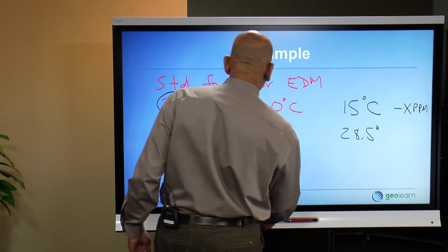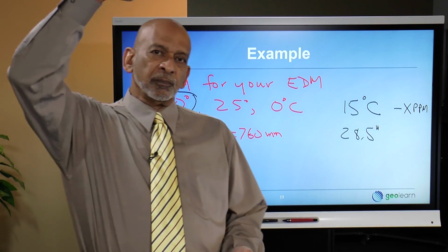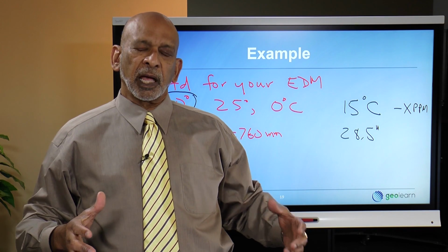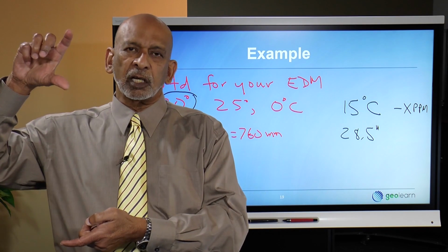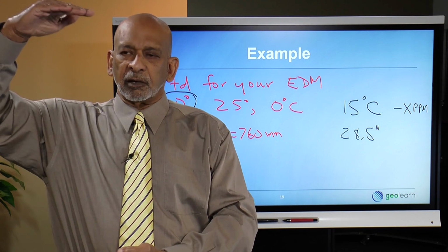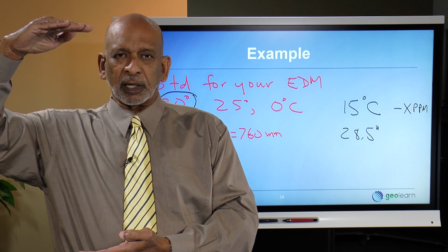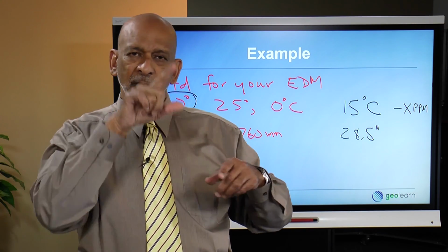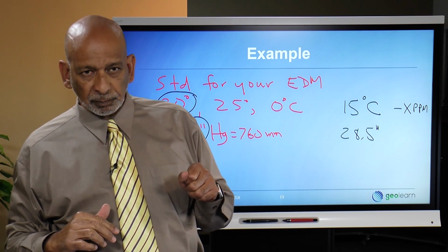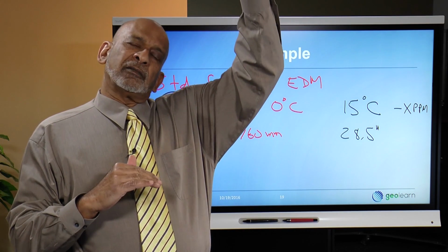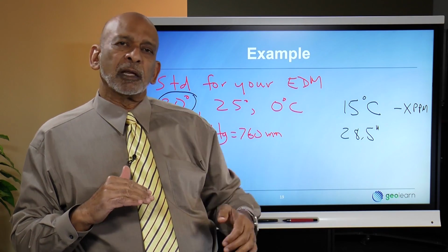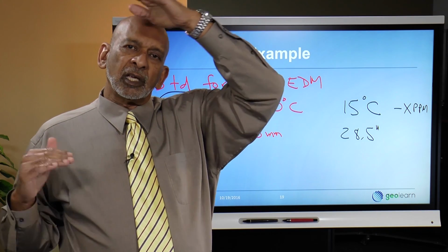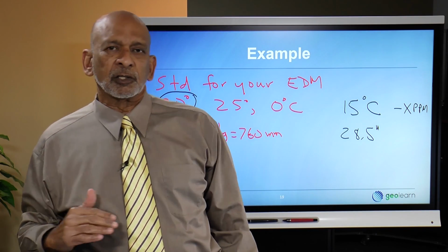Now remember what pressure means: atmospheric pressure. When you have a barometer, what you're doing is measuring how heavy the air above the barometer is, and you do that by comparing it against a column of mercury. A column of mercury that's almost 30 inches tall, 29.9 inches, exactly balances. They usually have a U-tube, sometimes referred to as a manometer, that tells you the weight of the column of air. So when the pressure is 29.9, the weight of all this atmosphere above you equals the weight of 29.9 inches of mercury.